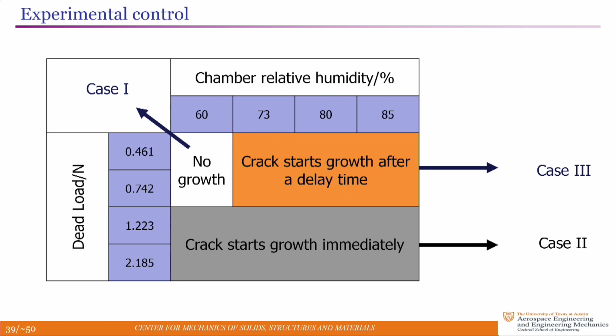And again, the reason why water accelerates the crack, my conjecture is that you've allowed water to come in contact with the fracture process zone. It infiltrates into the process zone fairly easily because it's liquid water, not vapor. And it lubricates. It swells. It allows greater mobility for the molecules to unravel, and the crack process speeds up as a result. Is there an effective opening mode because of the swelling, you think? No, the energy required to move the molecules is now lowered because of the mobility. So just the mobility, yeah.